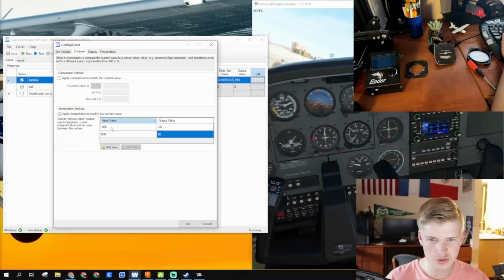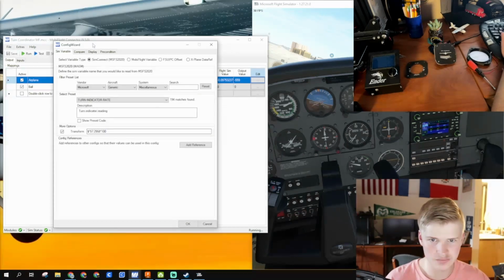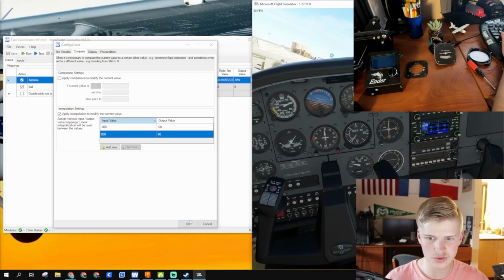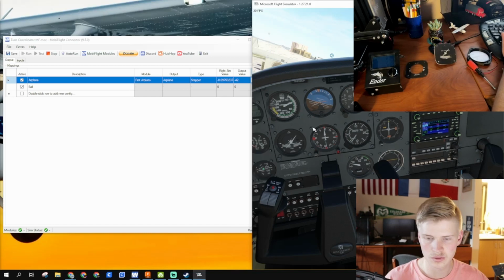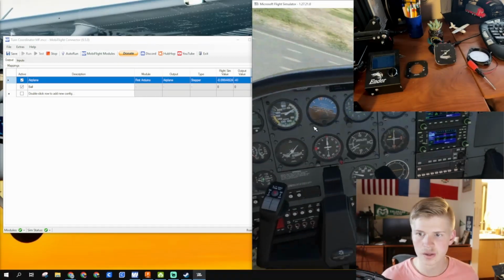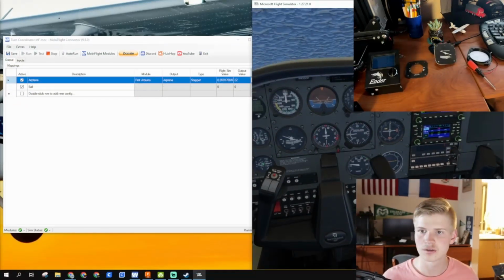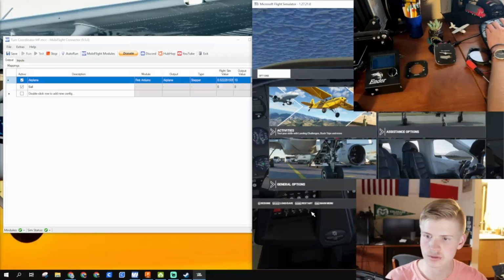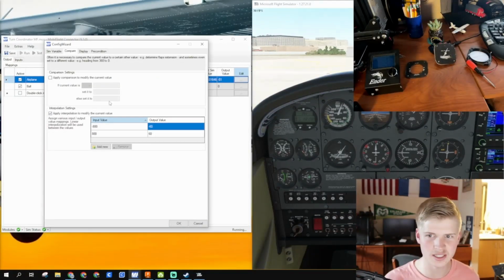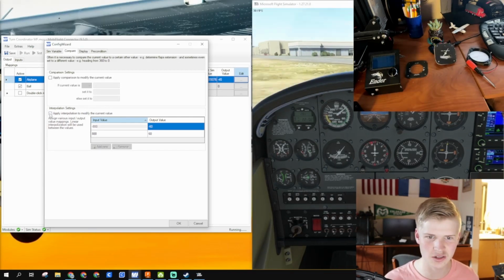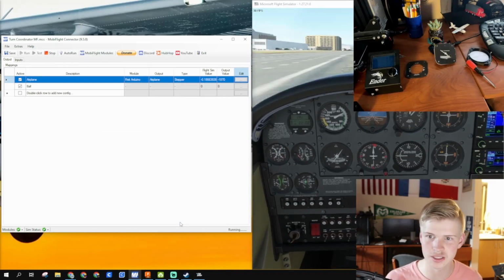I'm sorry I confused you right here with this 800. This is actually a better value. I saw this 60 and assumed that was, from my notes, the stopping point, but if you go over here, run, whoop, it does, woo. Yeah, it does look like it evens out closer to 80. Let's restart this flight. It says 60 right here because of our interpolation table. Again, we maxed out the stepper at 60, so let's turn that off and see what value we actually get.